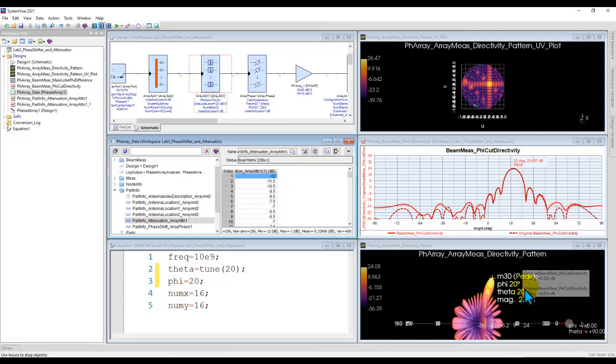Also, the beam direction is still at 20 degrees, and you can steer this beam in all desired directions to make sure your 4-bit phase shifter is able to steer the beam with the precision you are really looking for. All right, so this was all about quantization and how you see the results. And here in the phase shifter, because I used a 4-bit phase shifter, the phase shift among different branches is now restricted to 22.5 degree increments, as you would expect.